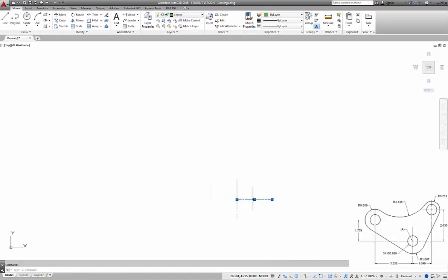I could also grip and then move this into the center, and what that will do, using the grip tools, I can then either A, manipulate one end by picking and stretching, or I can select the center and just shift it back to that midpoint. And now I've got a fairly accurate location of where this needs to be.